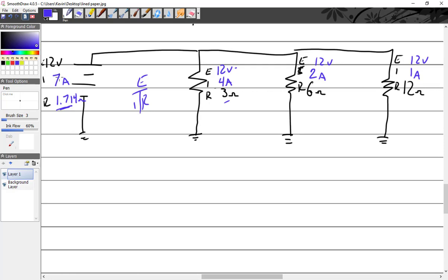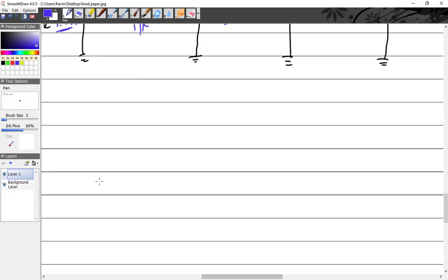Just like I do on a series circuit when I'm taking a test or checking a paper, I add up all the voltages and it better come near the total. Doesn't have to be exact, but it better be close to the total. And same thing here. So I'm going to add up all the amperages, and it should be close. All right, one more.